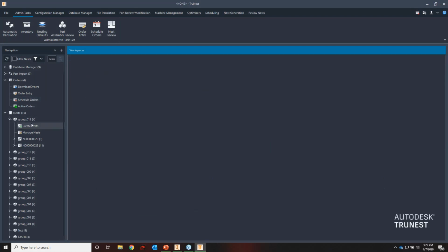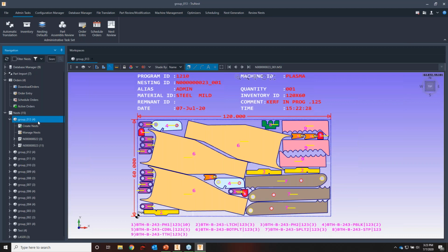Additionally, it's running another optimizer called sheet cutting during that process, which leverages processing of the sheet into smaller pieces, so it's easier for the operators to remove those from the machine bed as well. And lastly, during that step, it also runs the post-processor for each plate. So it's generating all the NC code with all the optimizations and toolpath optimizations I mentioned before, and getting that prepared to send down to the machine.